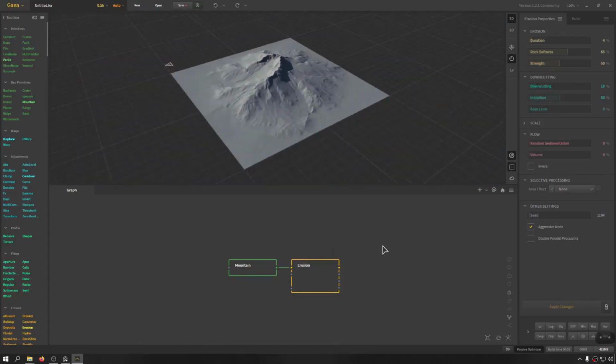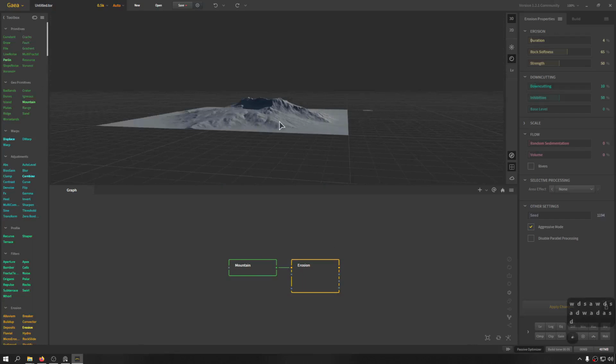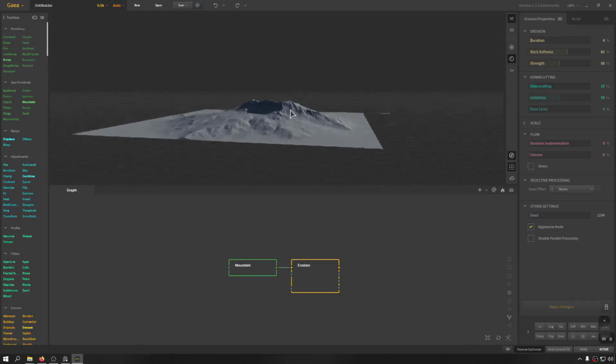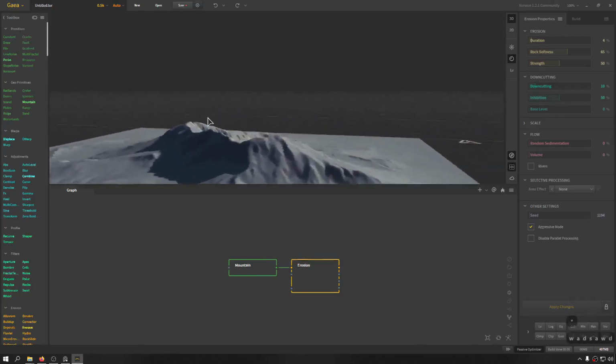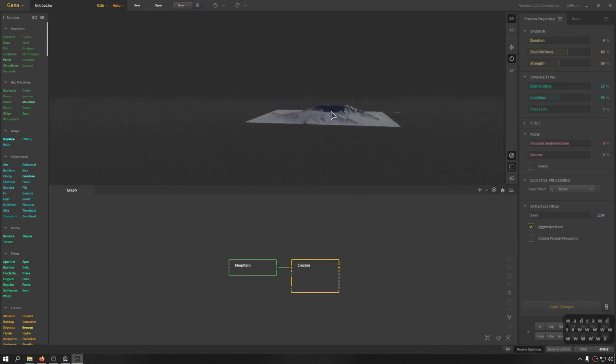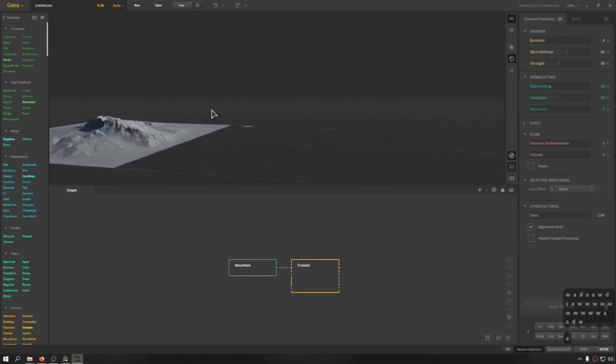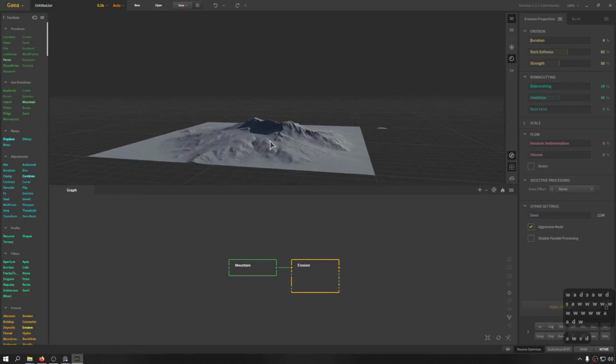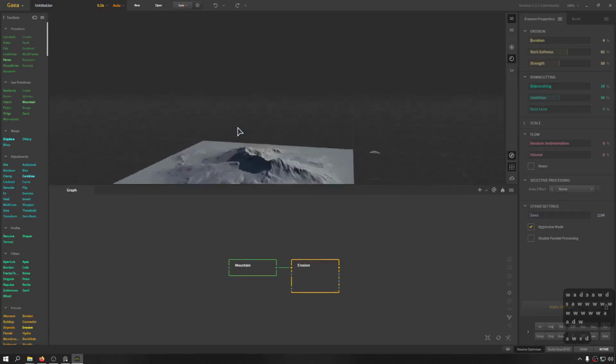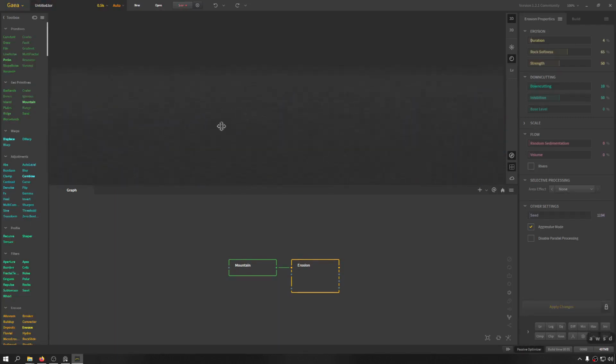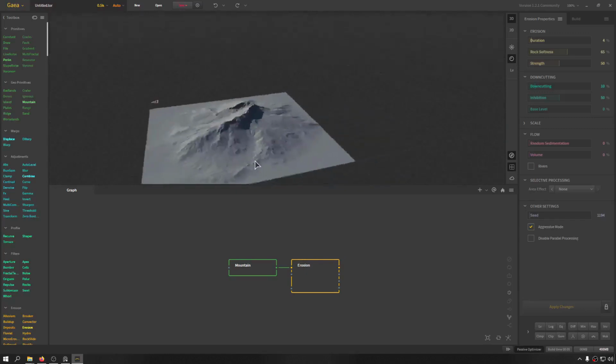So in here, there's a node-based software that we can create a lot of awesome terrains. If you click on this 3D viewport here, using the WASD, you're able to move into the terrain and see it from as many sides as you want. And for rotating around the landscape, you hold down Alt to assign a pivot, and you rotate around the landscape without any problem.